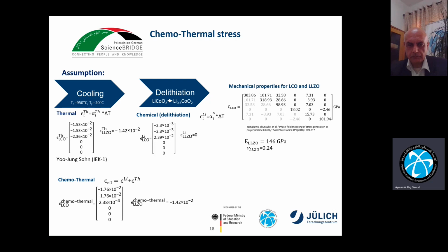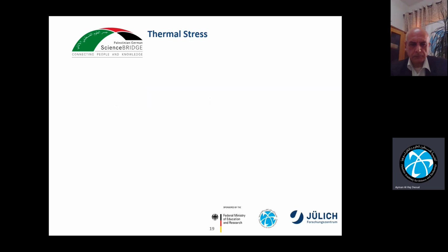Because we have anisotropic behavior of LCO, this is the compliance matrix of the system of the LCO, and we have also the elastic modulus of LLZO and the Poisson ratio of LLZO. We use a symmetric boundary condition to do this simulation.